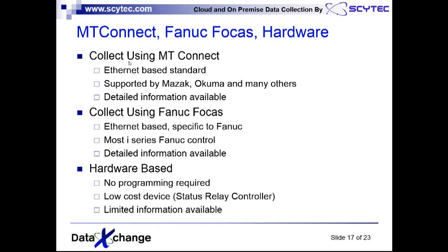FANUC FOCAS is a similar concept. It uses Ethernet as well, again, wired or wireless. It's specific to FANUC controls, and most i-series controls will have this capability. Again, you can get a wealth of information, such as the overrides, the feeds and speeds, things like that.